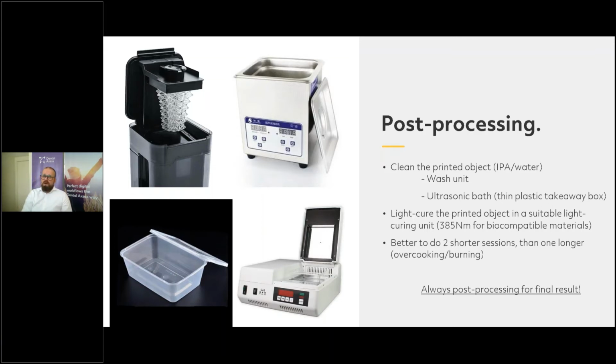And when you are light curing it, it's just better to have two shorter sessions than one longer, so it doesn't overcook or burn the material. Normally it's about an average of 15 seconds for an exposure. There's no exposure during printing.